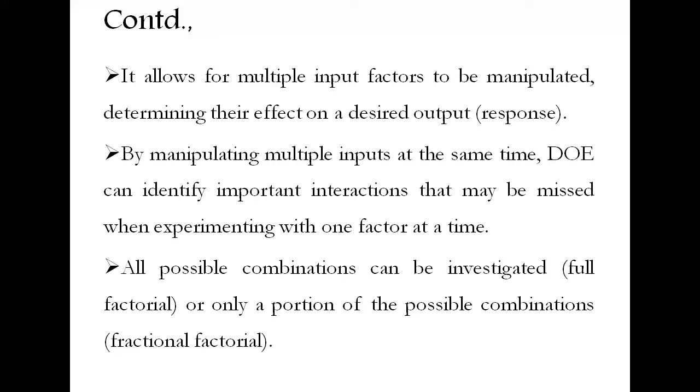So what is the difference between full factorial and fractional factorial? It depends upon how much money the experimenter invests, and based on this you conduct the experiments. Full factorial means all the experiments have to be conducted, for example 27 experiments means all 27 experiments have to be conducted. Fractional factorial means the experiments are conducted only partially. We get the output responses only for the conducted experiments.